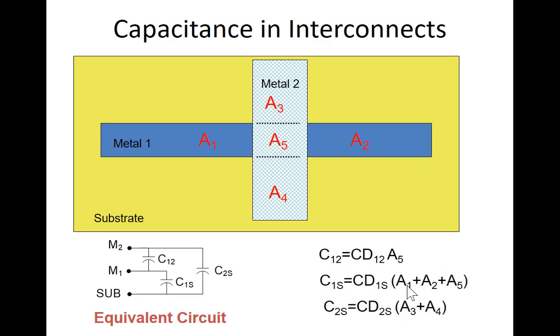You mean the substrate in between metal 2 and metal 1? There's no substrate in between. The substrate is the wafer we start with. So if you look at how this is fabricated, we'll have substrate here. Someplace out here there might be some transistors. And if we have this interconnect, there'll be a big insulator here. This is an insulator. And on top of the insulator, if you look at this cross section, we'll see metal 1. This is metal 1.